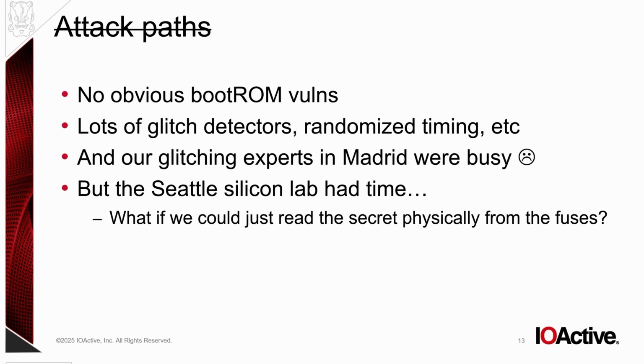It's very cheap, and it's some way of putting a unique identifier into that actual chip. You couldn't do that really any other way. You could do it in Flash, but it doesn't have a Flash. You can't do it in ROM because ROM is a mask. You'd have to make a new mask for every chip, and nobody's going to do that. That would be ridiculous. A fuse is just a good way to put a unique ID on an actual device itself.